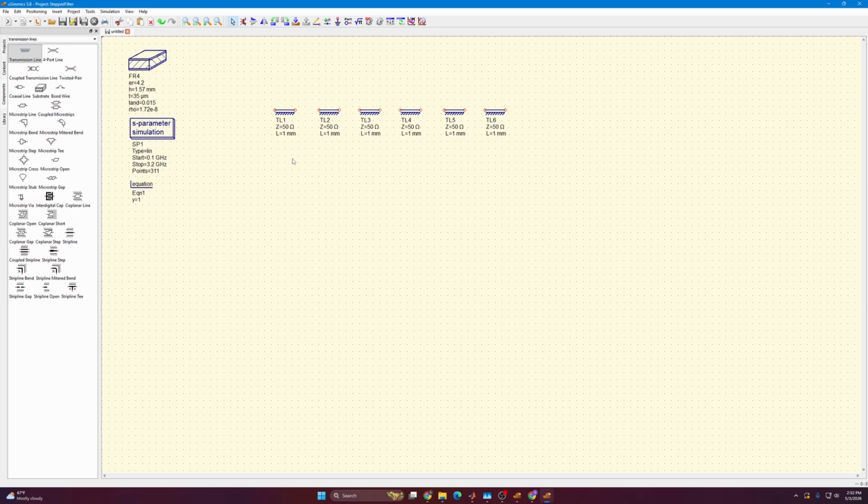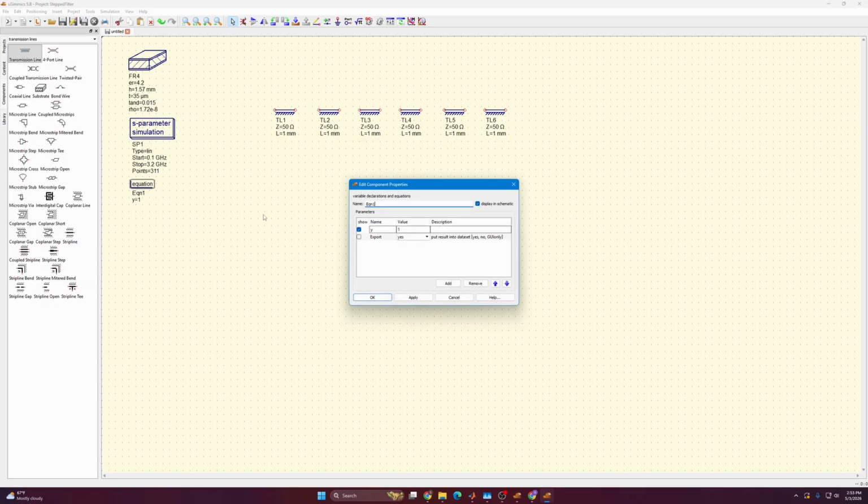So for ideal transmission lines, the speed of propagation here is going to be the speed of light. So that's what the equation block is for. We're going to be able to actually implement a vector that uses degrees to define our transmission line lengths. So let's go ahead and get that started. For our low impedance line, we're going to use A. We're going to get a couple more here. So we need our frequency and our speed of propagation, which is the speed of light.